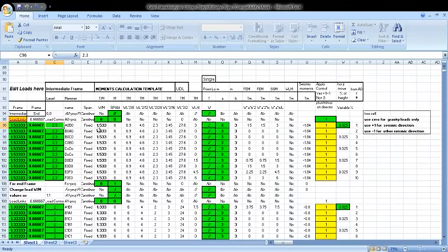So we can say load generally comes on beams, and this load is width per meter, or the span. Span means length of beam or column. Then you can say WL square over 8, this is for simply supported bending moment.